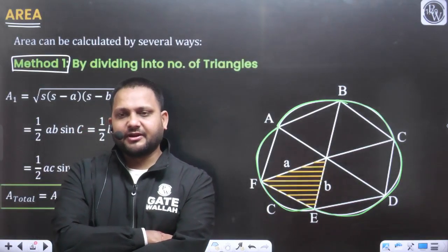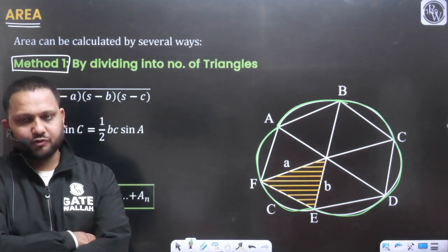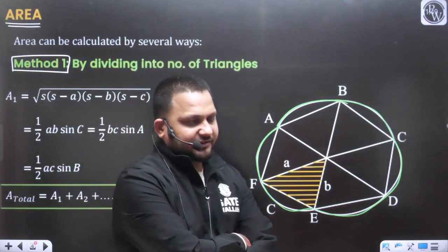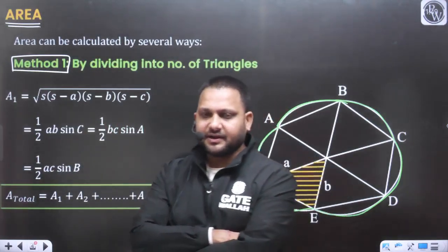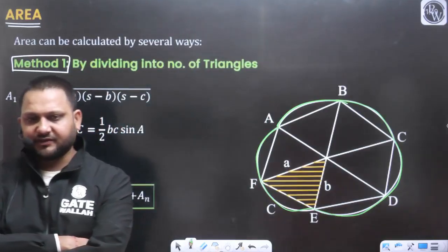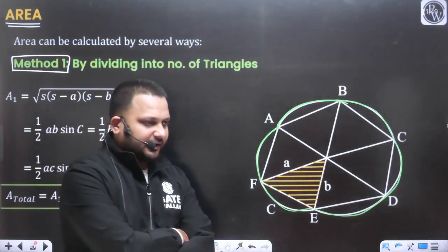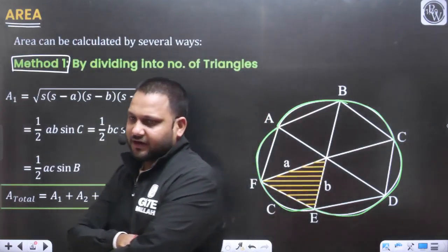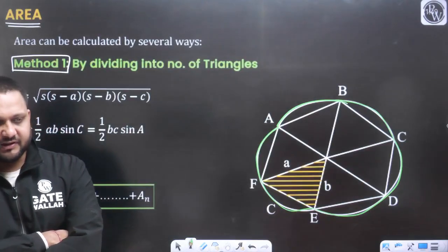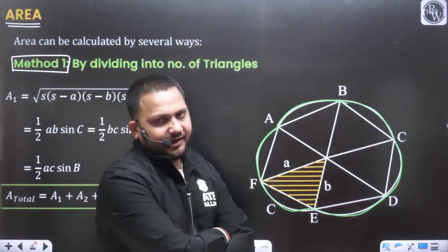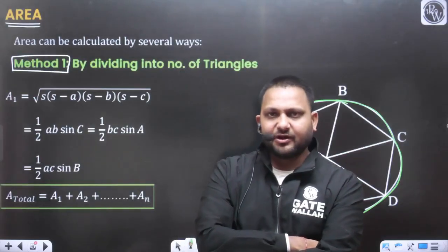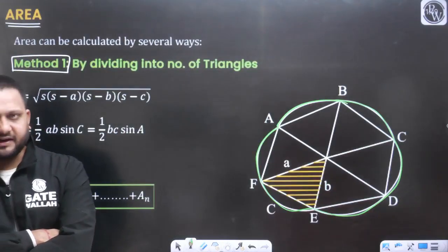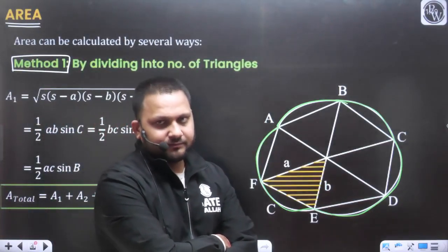Whenever we follow the triangulation approach, any angle of this triangle should not be less than 30 degrees, and should not be greater than 120 degrees. If all the angles are in the range of 30 to 120 degrees, we will say that the triangle is well-conditioned. If any one angle of the triangle is not in this range, we will say that the triangle is ill-conditioned.